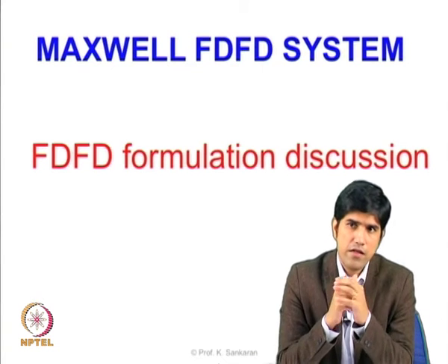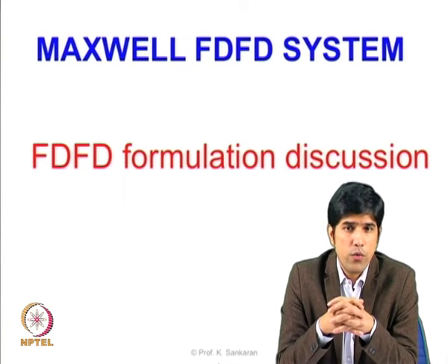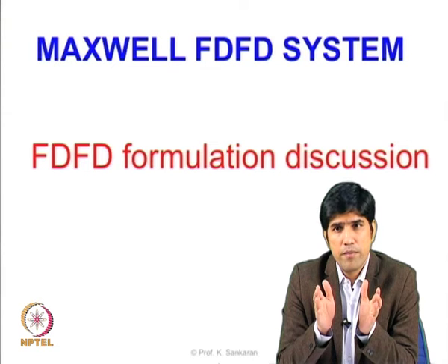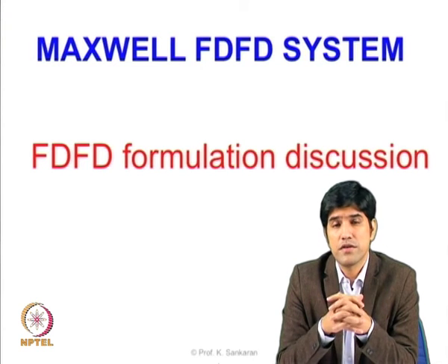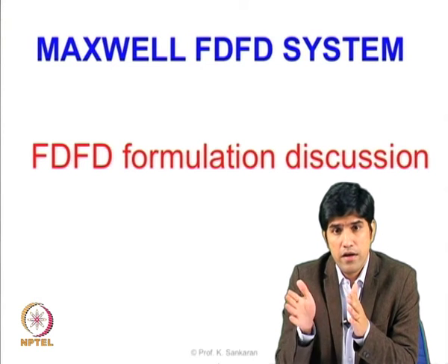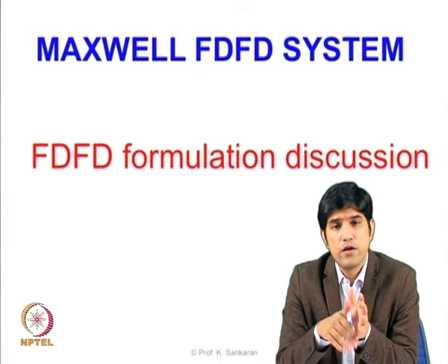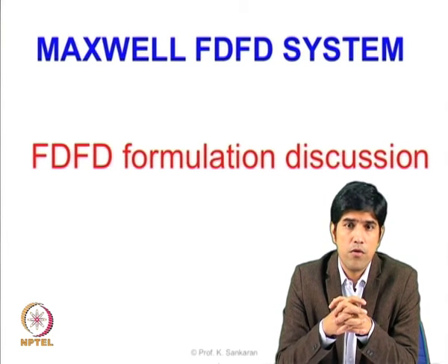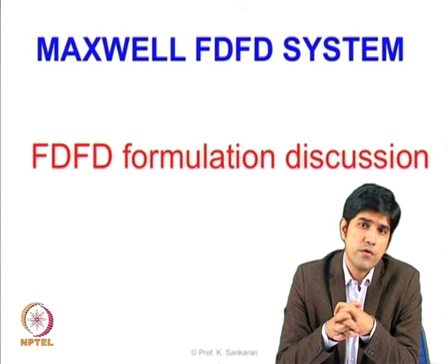So in that kind of cases, what I would suggest is doing a time domain simulation with a broadband pulse, where you can pretty much have the broadband information while running in a time domain simulation and doing the frequency domain transformation using a fast Fourier transform or any of the FFT routines that you have.